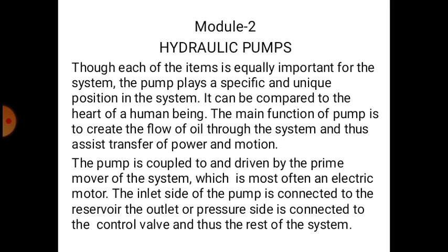The pump is coupled to and driven by prime mover of the system, which is most often an electric motor. The inlet side of the pump is connected to the reservoir. The outlet or pressure side is connected to the control valve and thus to the rest of the system.